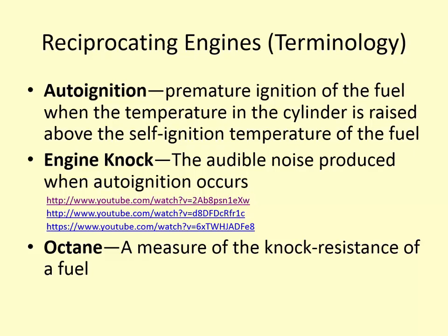If for some reason you're using a very low-octane fuel or your engine timing is off, then you can have auto ignition, which is where the fuel is being compressed to very high pressure and it ignites without even having the spark plug spark. Okay, this is never a good thing in an engine, and it's something you want to avoid because it causes engine knock, which is an audible noise produced. And we're going to hopefully watch a little video that will show that.